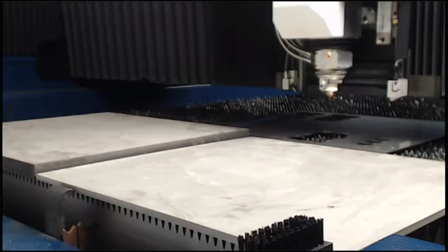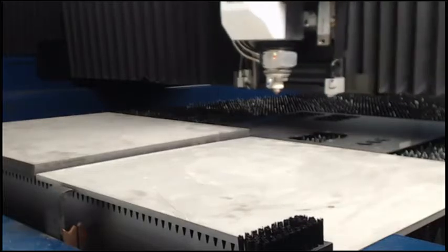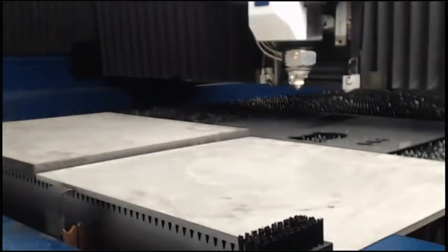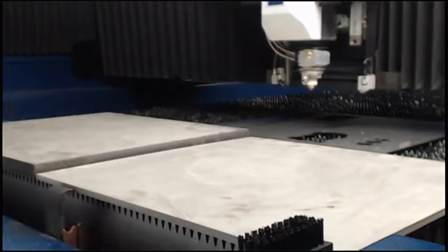Conversely, if it says, hey, this material is actually pretty good, it will speed up to 20% over what the base, 15% over what the base feed rate was. So you'll either go slower to make sure that the process is consistent, or it will actually go faster if the material can support it. So that'll be something we'll be doing in the future.